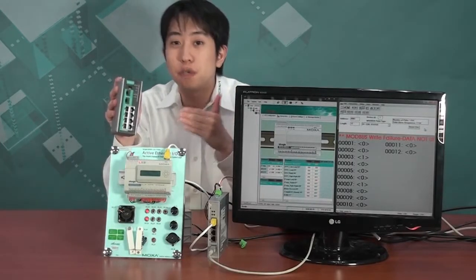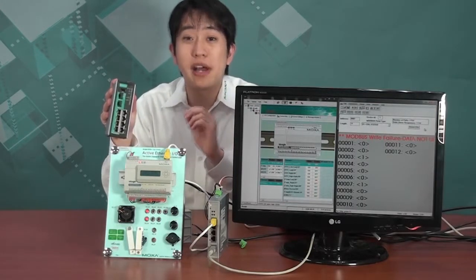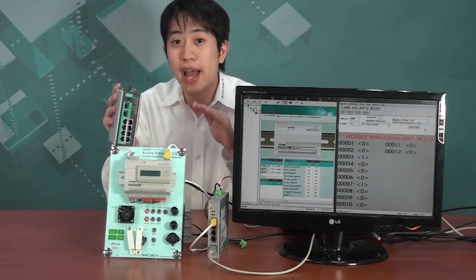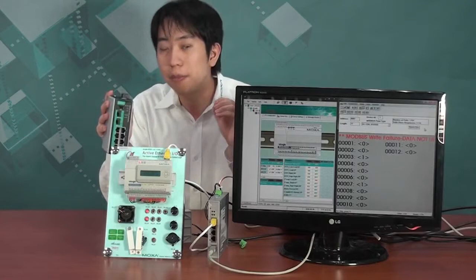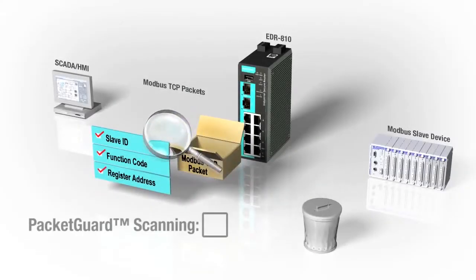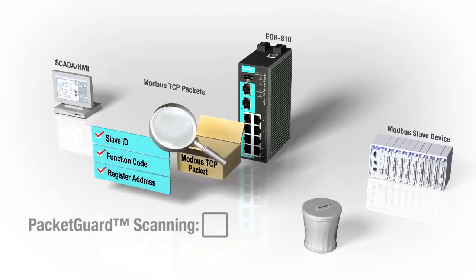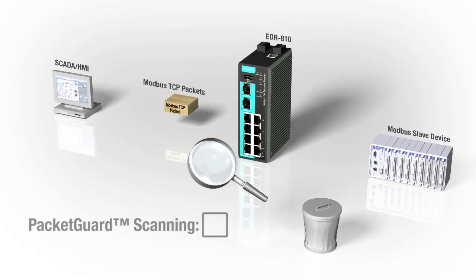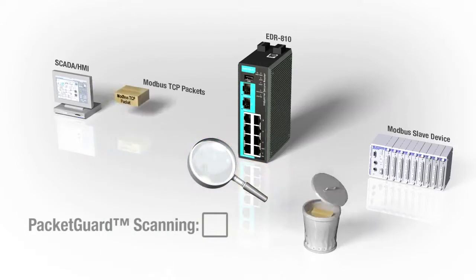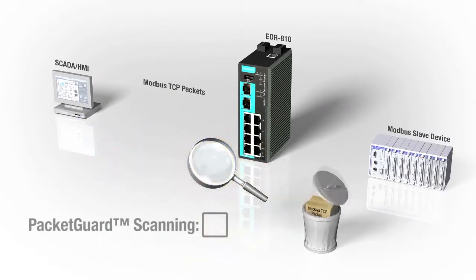An industrial secure multi-port router. Now, the EDR-810 has a built-in firewall and VPN functionality. And critically for industrial networks, it also adds deep scanning of industrial Modbus packets, what we're calling PacketGuard. PacketGuard performs deep inspection of every individual Modbus TCP packet and verifies its slave ID, function code, and register address. Modbus packets that do not meet its requirements are dropped. This adds one more layer of protection on the application level to an existing firewall.